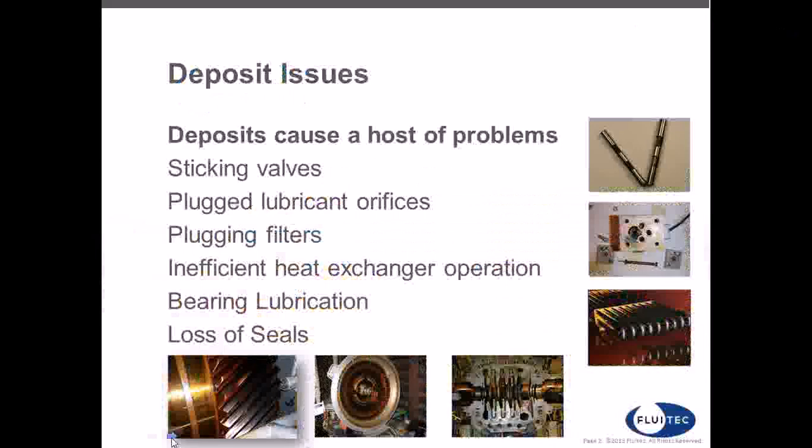These deposits are often sticky in nature and can cause components like valves to stick. They can plug up small oil lines and restrict oil from flowing in certain parts of the system. Some types of deposits can slime over filters and result in premature filter life.